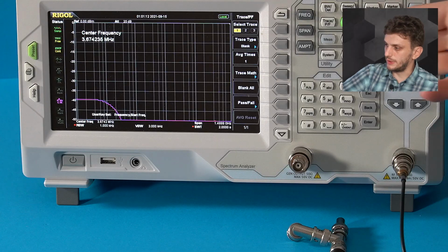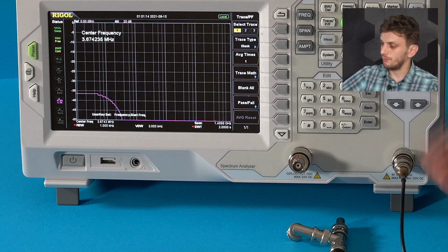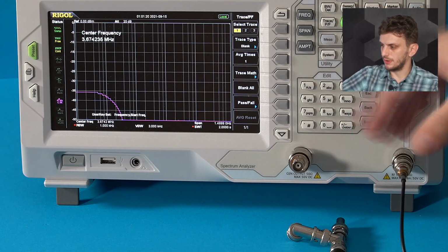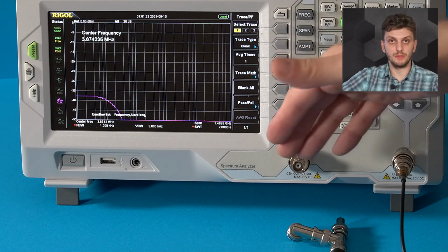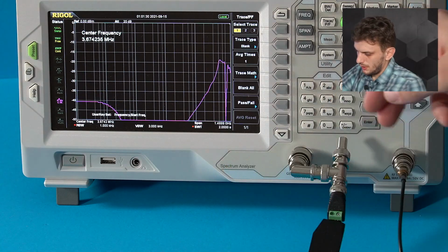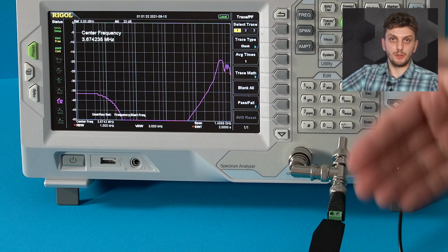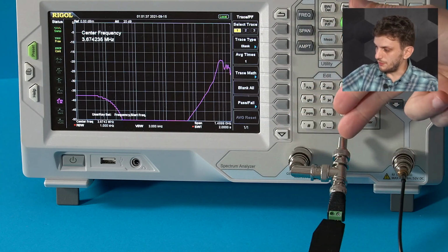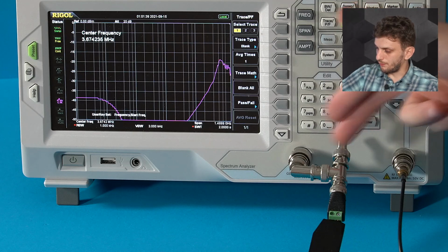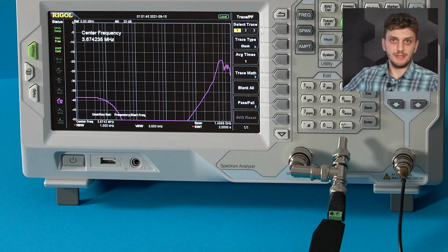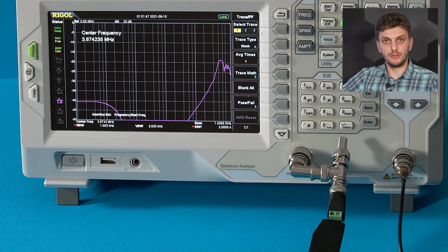So next, let's check out the bandwidth of the probe, and for that I prepared the spectrum analyzer, and I'll be using the tracking generator function. So I already performed the calibration, so to normalize the output in reference to the input. And if we connect our probe, since the probe doesn't have a proper 50 ohm input, it's a high impedance input probe, I have the 50 ohms here on a termination, and I got this T-junction thing. So this is not an ideal high-speed setup, but it will do for today.